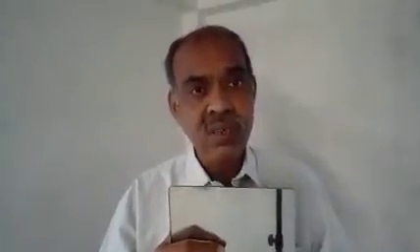For the rectangular case, the point of center of gravity was the point of intersection of the two diagonals, and that was the CG. This CG is at a distance of L by 2, and that distance was taken for the calculation. But this load is now triangular. Here L by 2 is not correct.